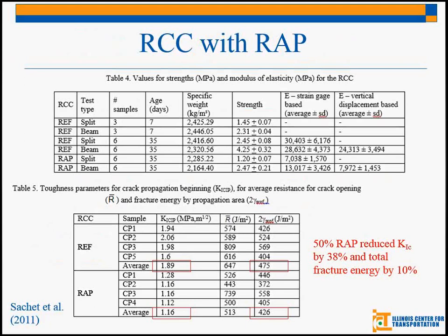And I'm going to talk about why running fracture properties is more important when we're talking about pavements a little later on. But they found that the use of RAP can significantly decrease your compressive strength, your split tensile strength, in addition to your critical stress intensity factor and your total fracture energy.